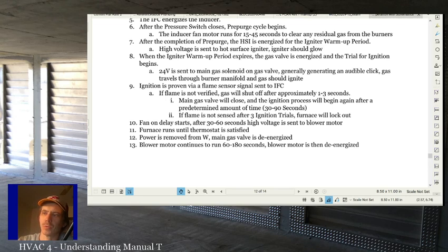It is possible that you'll have 2 flame sensors, one for the pilot, one for main gas, but that's pretty rare. Pilot lights are a very tried and true way to make sure that main gas comes on. They do a very good job because you've already got a fire right there. The fire will light the bigger fire, no problem. Whereas a hot surface igniter, even if it's glowing, sometimes will fail to light the gas off if it's not quite hot enough.